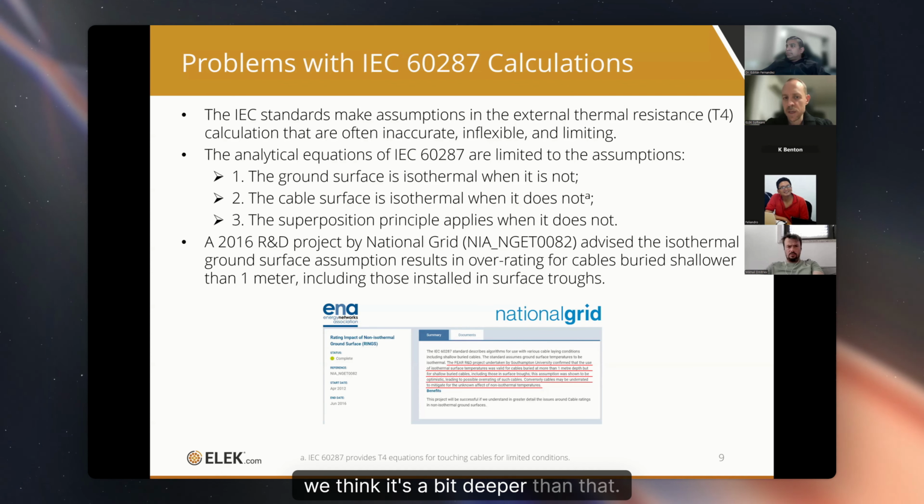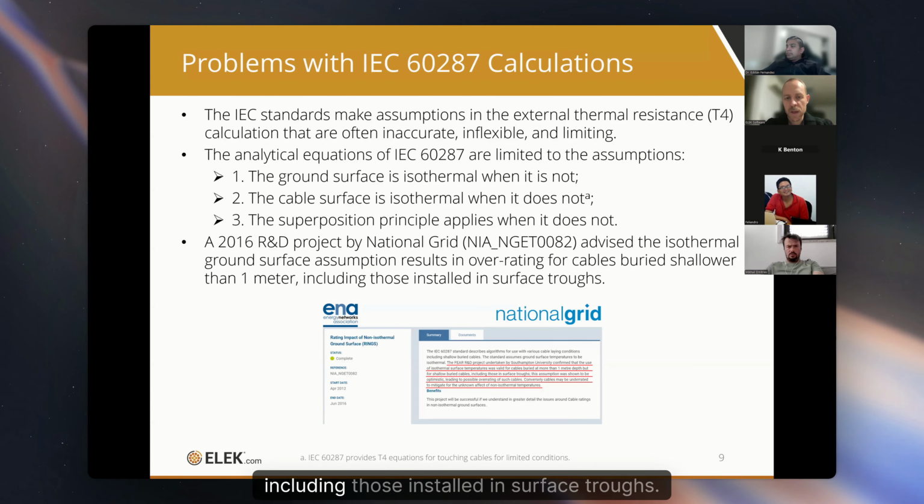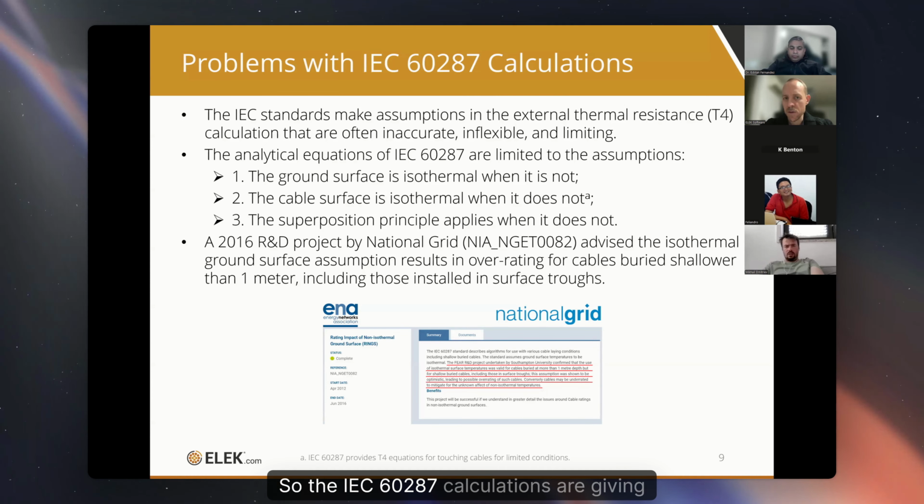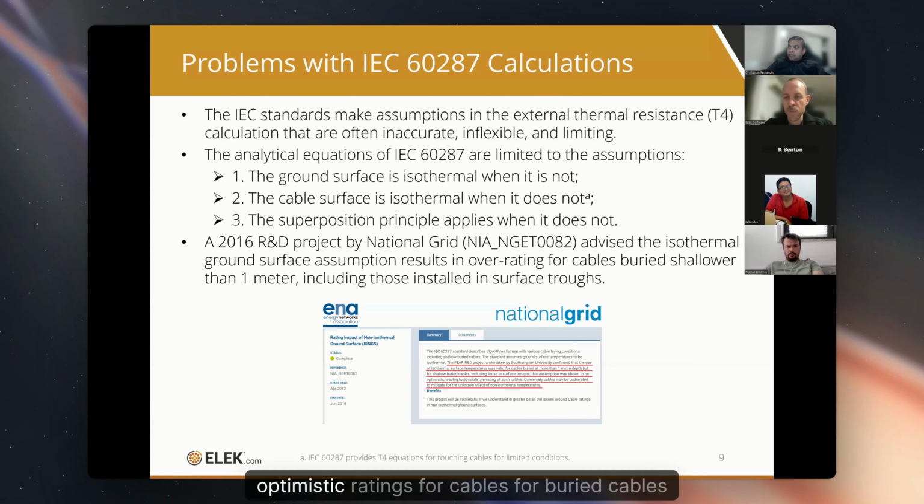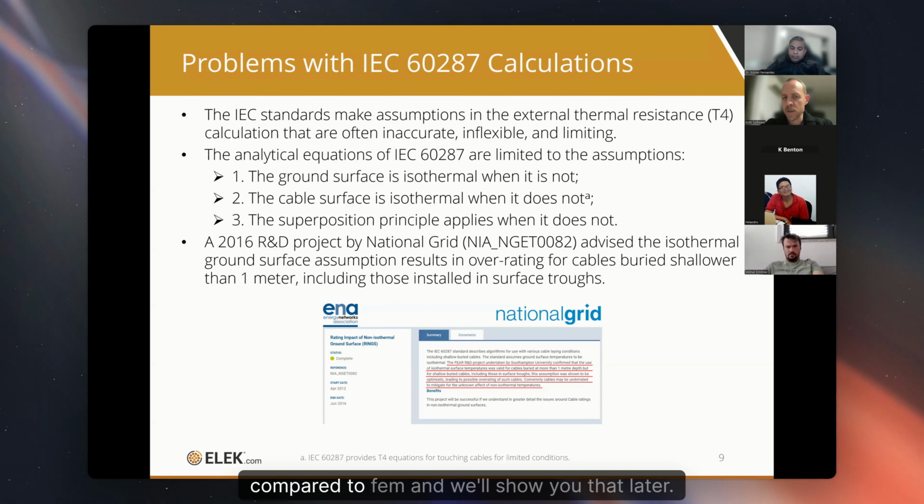We think it's a bit deeper than that. That's what we've found, including those installed in surface troughs. So the IEC 60287 calculations are giving optimistic ratings for buried cables compared to FEM. And we'll show you that later.